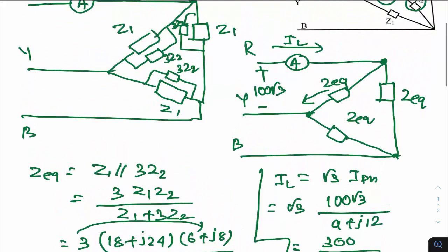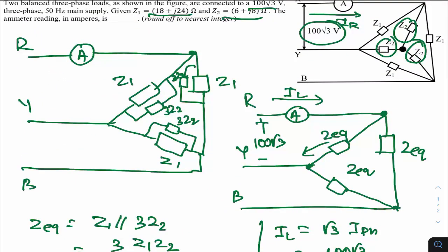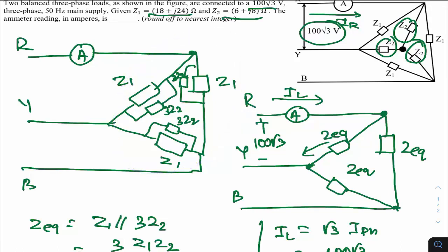So this is again a simple question. From the given complicated network, first we obtained this particular model using the star to delta conversion. Then I drew a simplified version of this. Then I figured out this is the current we need. Then by observing the structure of the delta connected load, it is easy to find the phase currents because the voltages are directly applied to the individual arms, or the phases. I can get the phase current. What is phase current? Phase voltage divided by the impedance.